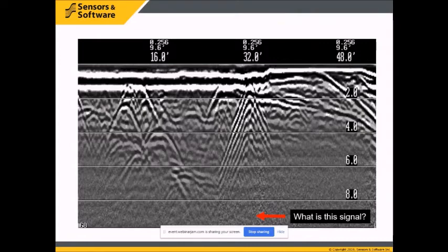It's important to remember that a GPR receiver does not only record GPR signals, it records radio signals. So it records the GPR signals and any other radio frequencies in its bandwidth. To us, these other radio frequencies are unwanted, so they're called radio frequency or RF noise.